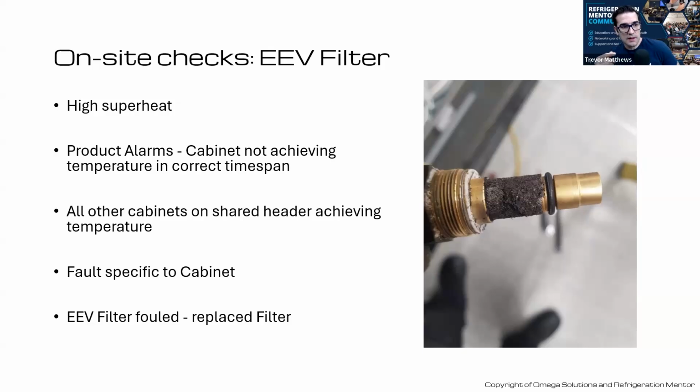Right now in the UK, you can blow out the CO2. You pump the circuit down, say you have 12 bar left in a low temp circuit, or 200 psi, because that's vapor left. Right now you can still blow out all that CO2 to the atmosphere. It's not against the law anywhere in the world, I don't think, at this point, or there's not much regulation, but we can release natural refrigerants.